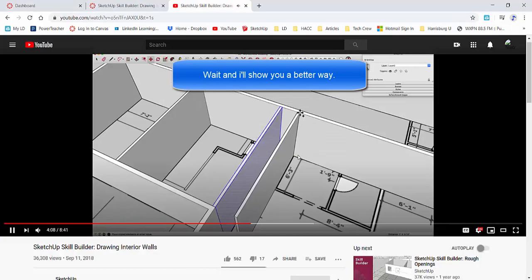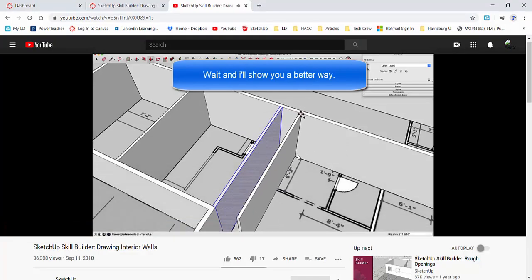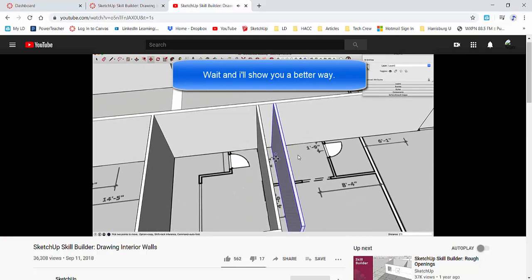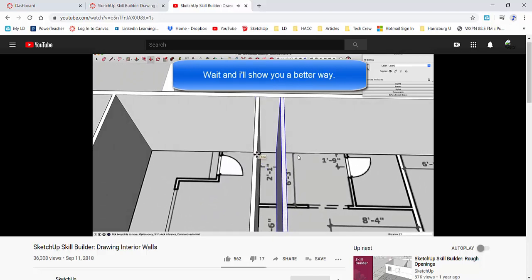That's Control on Windows, and I can start to pull it across here. So I'm going on the red axis right now. Now if I move this over 2 foot 1 inch, it gets me close, but not quite, because that is relative. So from this point to this point is 2 foot 1. It should actually be 3.5 inches further over. So again, I haven't changed anything.